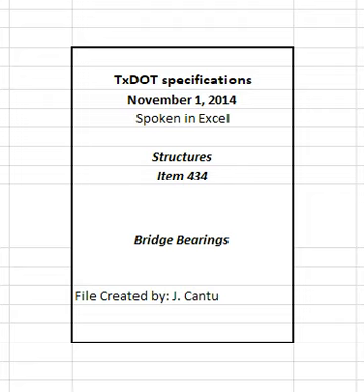Place HLMR bearings on preformed fabric pads as indicated in Section 441.3.11.6, Bearing and anchorage devices, unless indicated otherwise on the plans or the shop drawings.